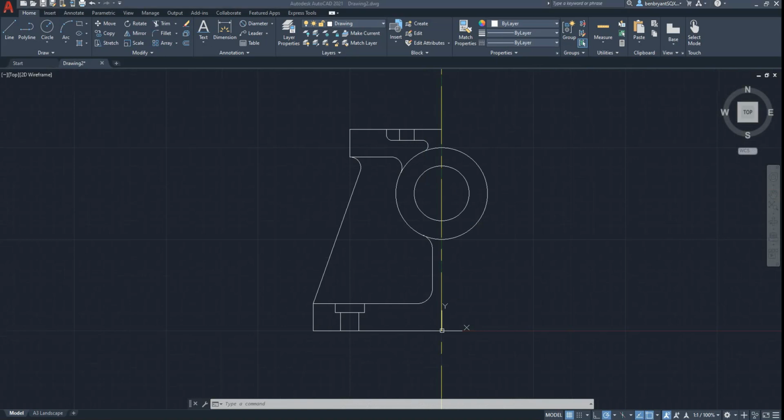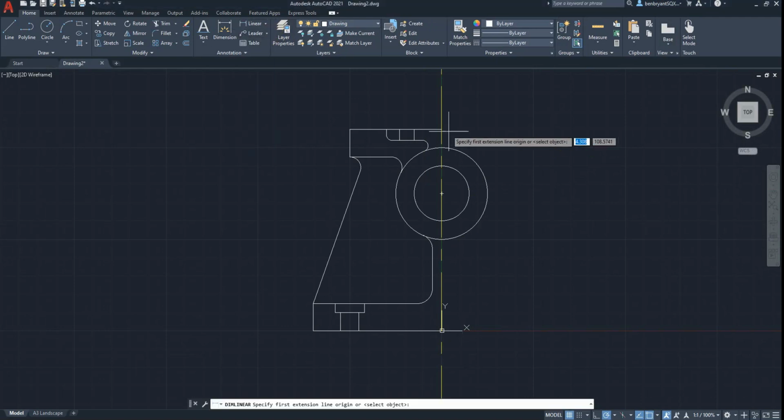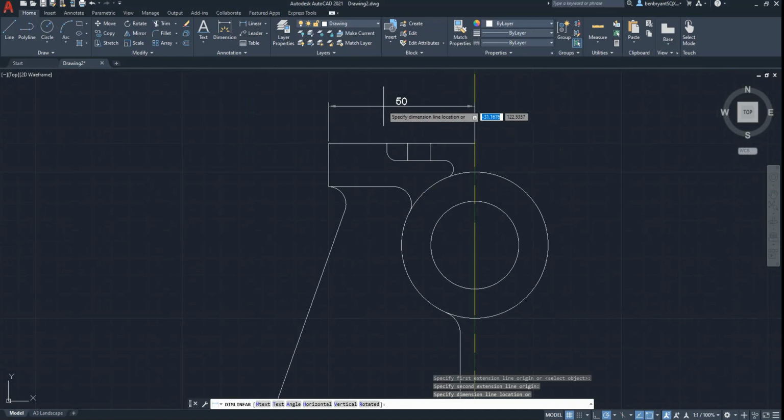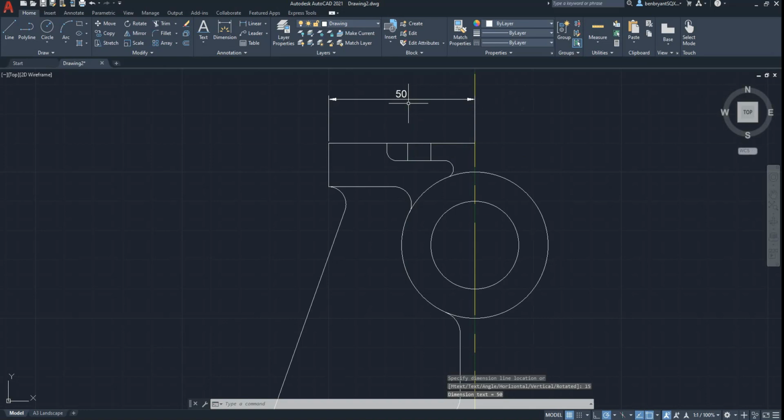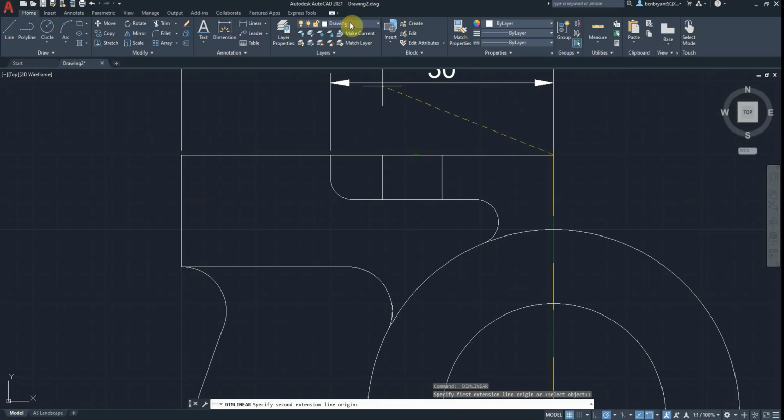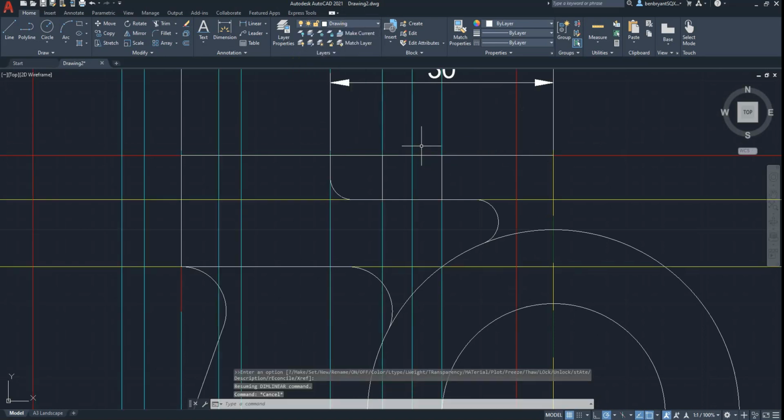Last thing to then look at is just dimensioning it all up. So what I've got along the top is a 50 along the top, a 50 for the lower bottom. So I'm going to start off using the linears. Okay, I'm going to kick this up probably 15 mil, because I think there's 3 underneath. So the same point again to this point, look at that, turn up, and then same point again to the center. So what you should really do is use the construction lines to pick up the actual points that you need,